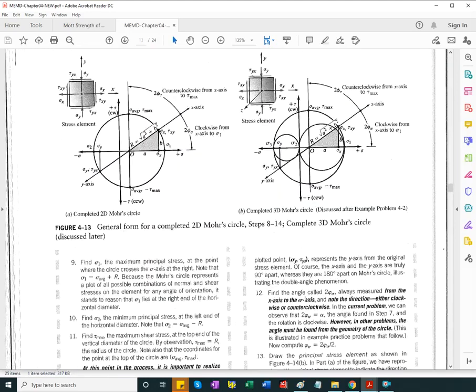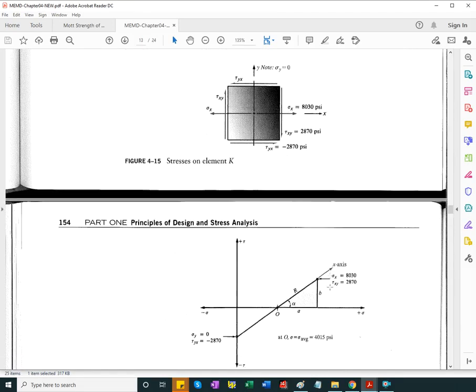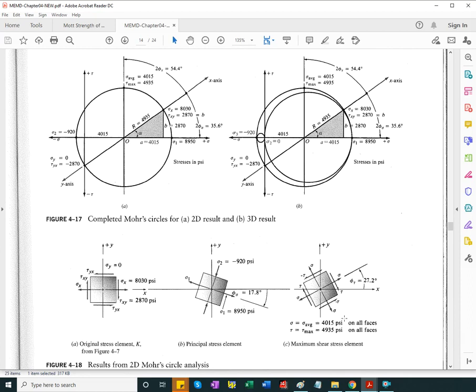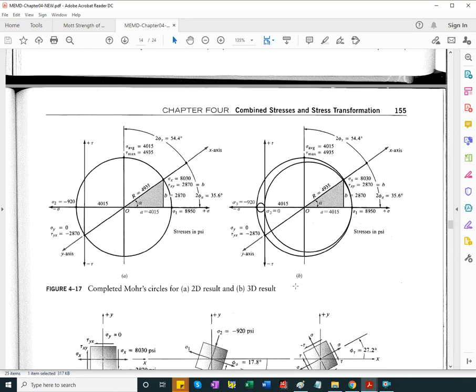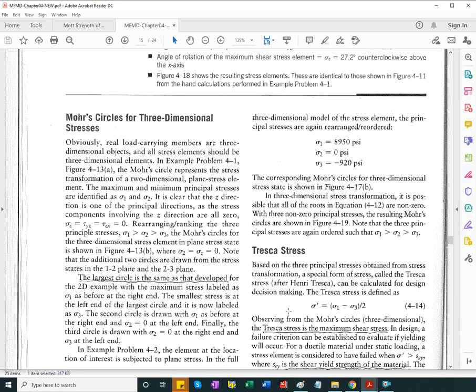Remember the additional step of showing the third of the principal stresses, which is sigma 2 in this case. Again, if we do just a 2D circle, it will be sigma 1, sigma 2. Otherwise, notations change to accommodate sigma 3 as being the lowest of the stresses. Some examples: they are just listing sigma x, sigma y, tau xy as values, various combinations of values, and draw Mohr circle with those.